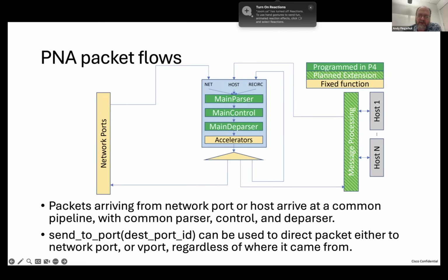Both payload checksum calculation and encryption are things that someone wants provided at line rate. TCP payload checksum offload at line rate is something where, if you don't have it, nobody is going to buy that NIC as a NIC. Because vendors care about selling devices, this will very commonly be done at line rate by whatever mechanism they choose.